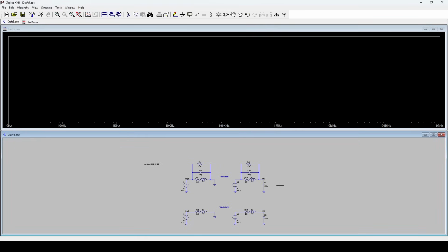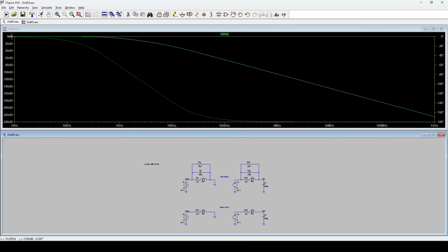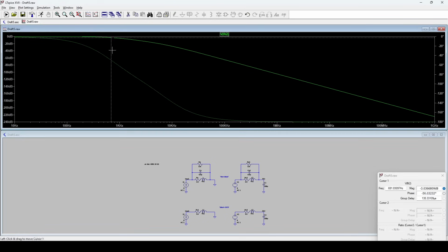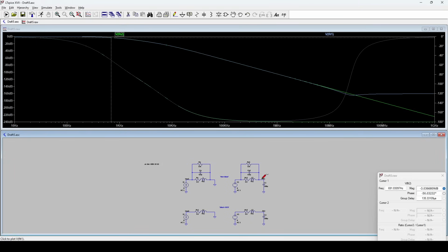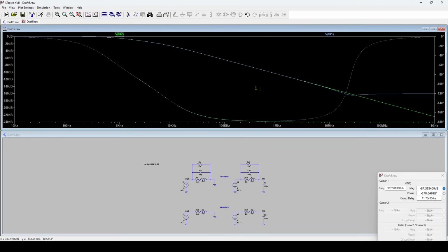Now if we apply that and check out the differences between these two low-pass filters, let's see the more ideal one, we have a 0 dB passband with a cutoff frequency at about 700 Hz. Comparing that to our more non-ideal filter, these again are very, very similar up to and close to the self-resonant frequency, after which our filter that incorporates these parallel elements now flattens off and tapers off and gives us a minimum possible achievable attenuation rather than a decrease in amplitude as we go up and up in frequency. So if you're looking at a certain attenuation above the self-resonant frequency, you need to be careful because of this parallel winding capacitance and the reduction in inductive behavior above that point.